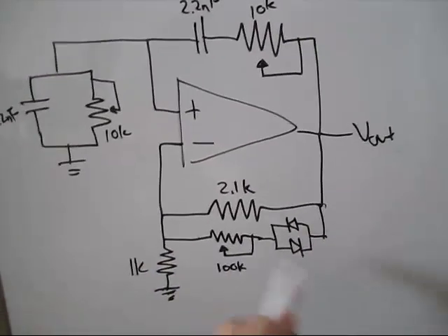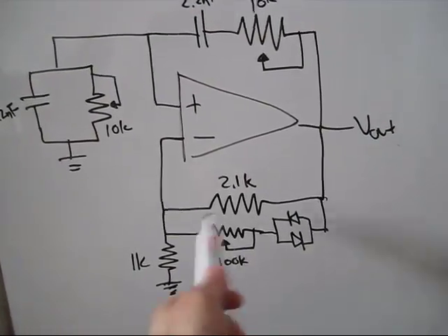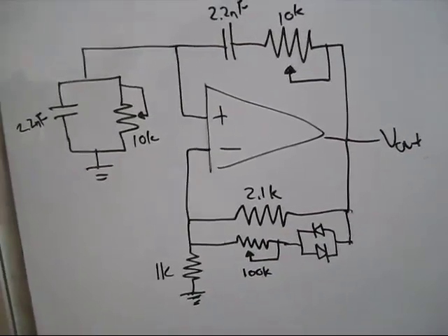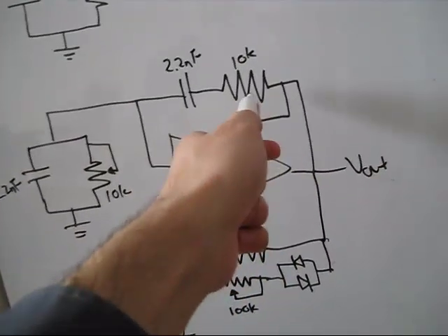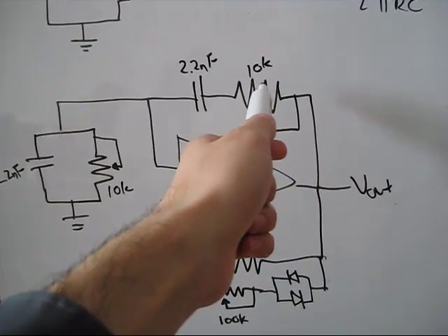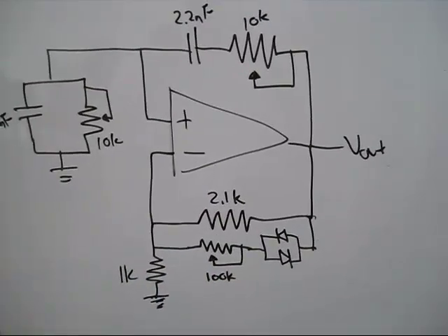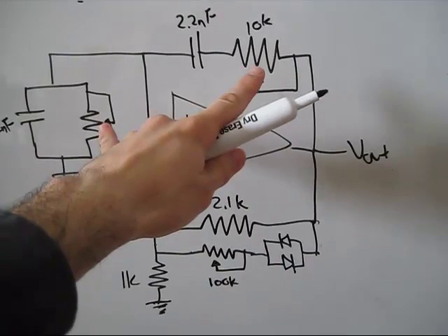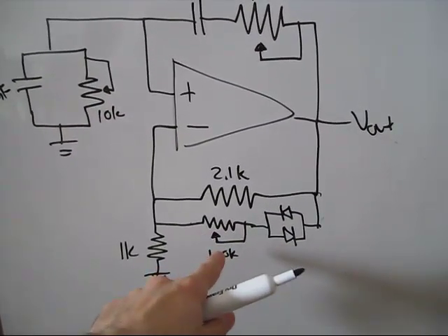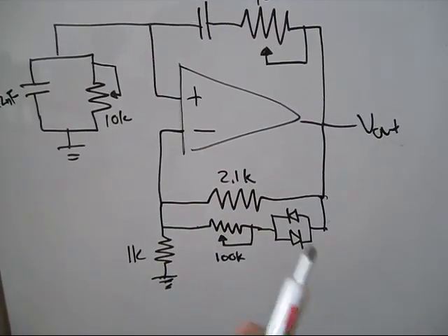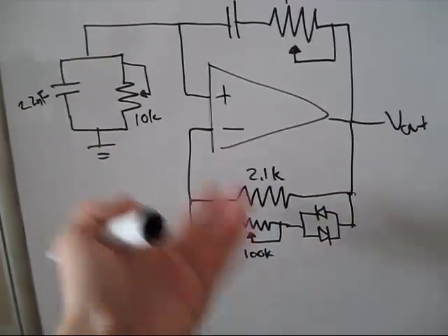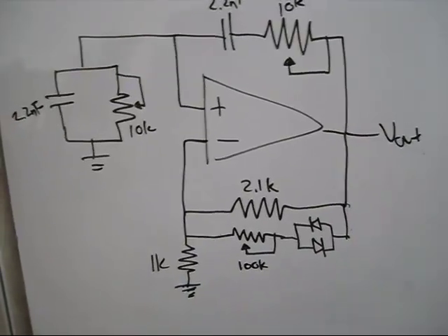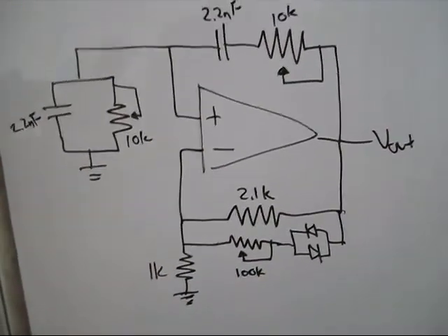So this produces the same sort of effect. It gives you that amplitude control that you're going to need to get a nice oscillator out of this. And this is what we're going to build up. Now, I don't actually have pots that are 10K or 100K. So instead we'll just use fixed resistors for those, and we'll change them to see how the frequency changes. And here we'll use like 47K with one of my 50K pots in series. It'll be close enough just to see what's going on. We won't be able to reproduce it exactly, but it'll still be pretty cool.